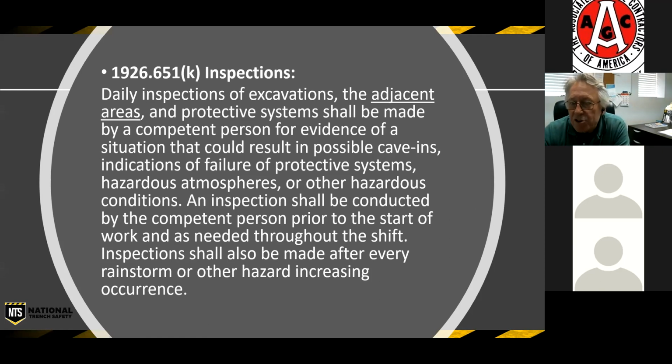The competent person is looking for evidence of a situation that could result in possible cave-ins, indications of failure of protective systems, hazardous atmospheres, or other hazardous conditions. An inspection shall be conducted by the competent person prior to the start of work and as needed throughout the shift. Inspection shall also be made after every rainstorm or other hazard increasing occurrence.